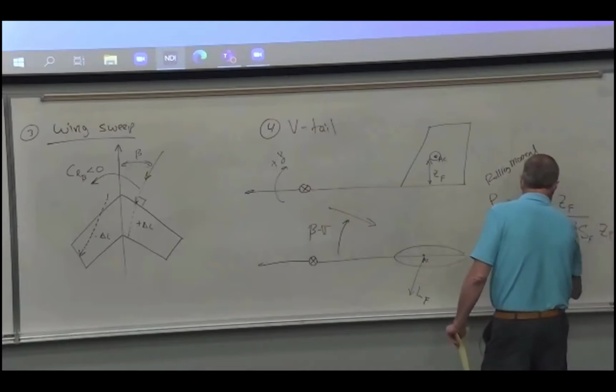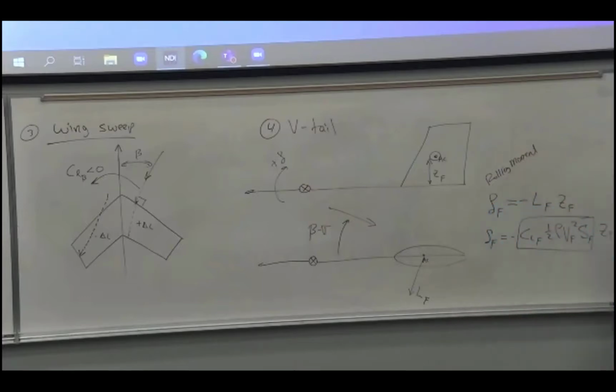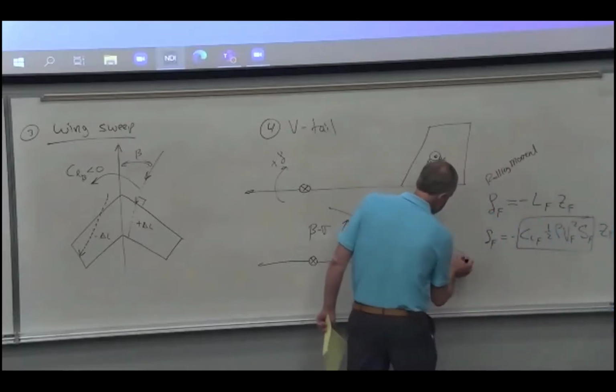So this is the exact same derivation. In fact, it's the thing that you had in the rudder derivation that you're doing on the homework, except here the CLF is generated by the rudder rather than the angle of attack. So that's where you get AR times delta R, because you get some lift due to the rudder. And we could even include that effect here if we wanted, right?